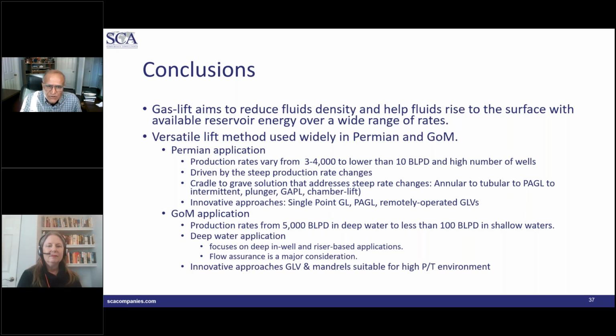The main challenge for gas lift comes if you do not have sufficient gas, right? And I have seen that challenge in some of the North Sea cases, where as the water cut keeps on increasing, you do not have sufficient gas because you already have made a sales commitment. Now, you may argue with me that this is a closed loop system, so the gas is not going to go away, but there are always some gas losses.